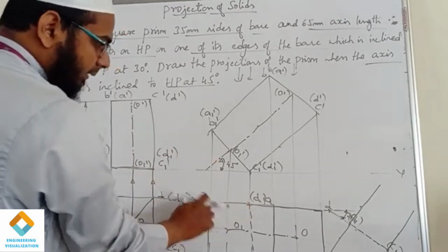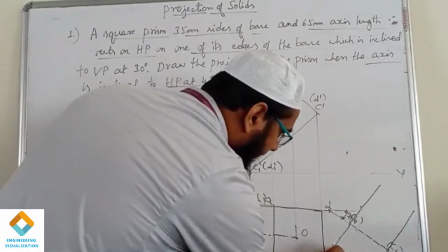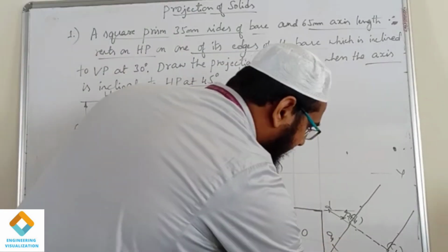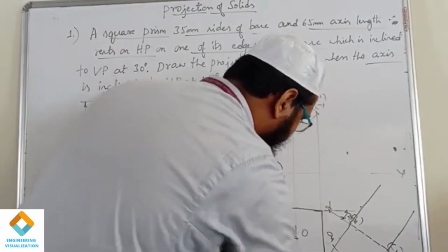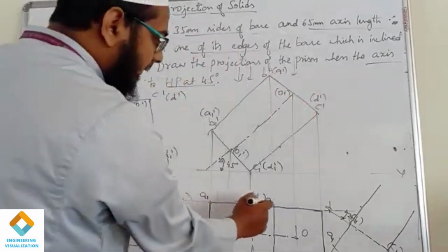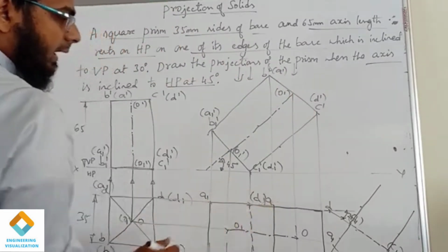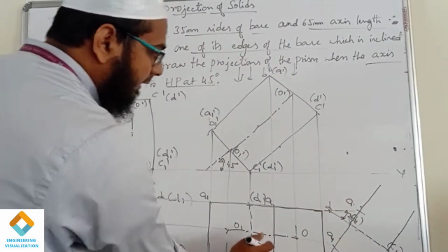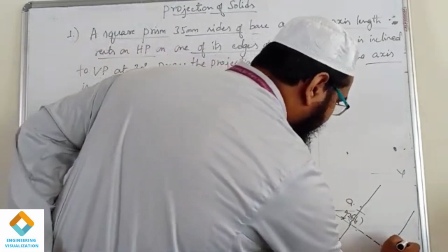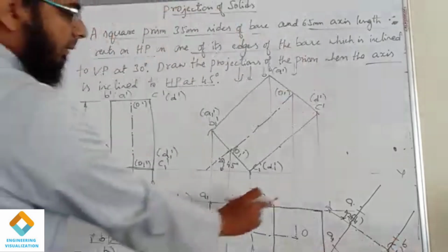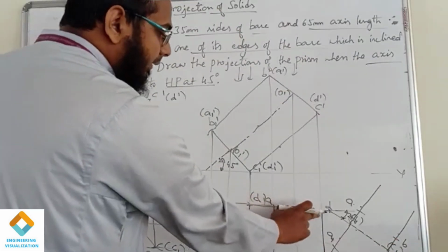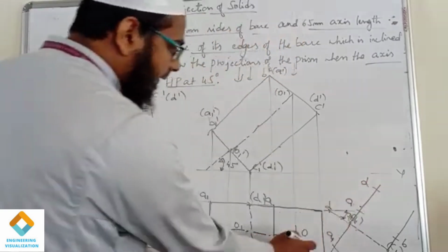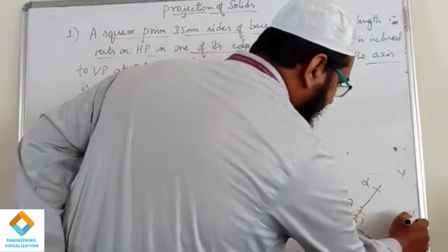After that we take the compass and measure from D1 to A1 and cut the arc. This is A1. Similarly, C1 to B1, you can cut the arc. That is B1. Similarly, D1 to A, you can cut an arc. C1 to B, you can also cut the arc. Now from A to D, by measuring with the compass, we can cut the arc. Similarly from B to C also.